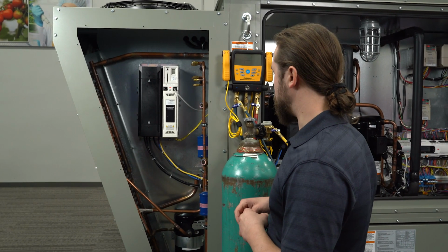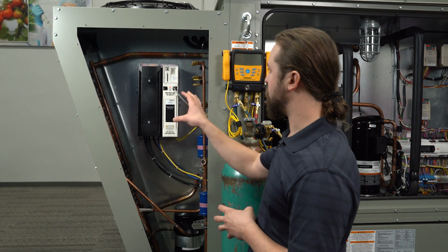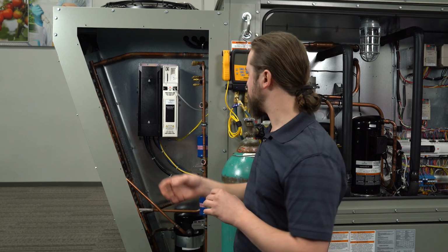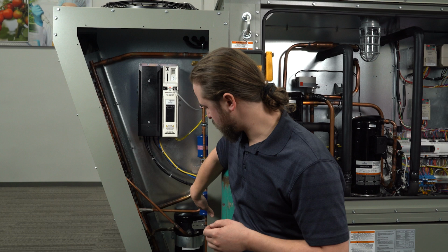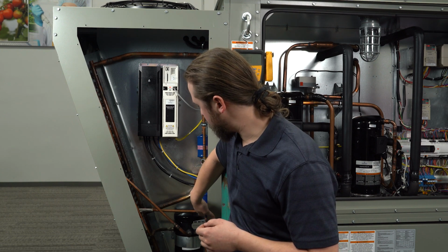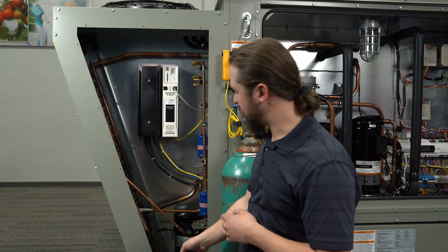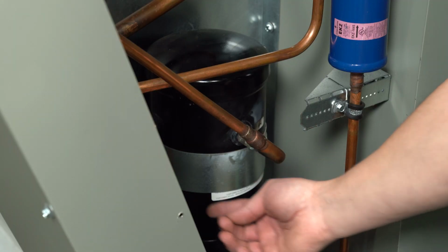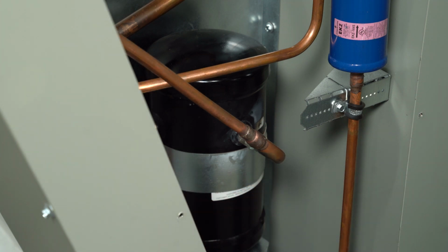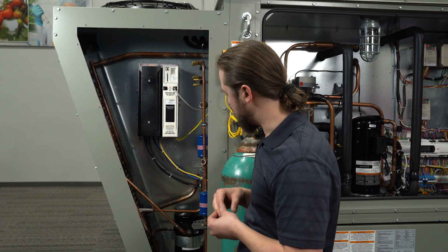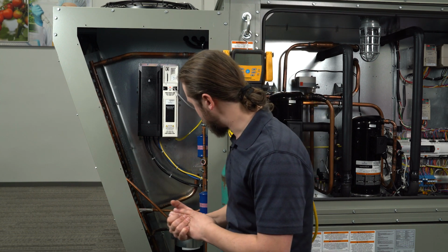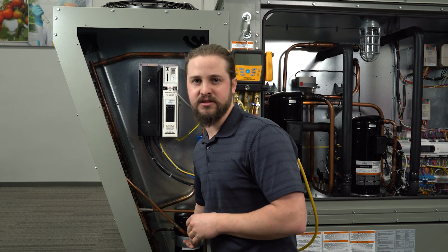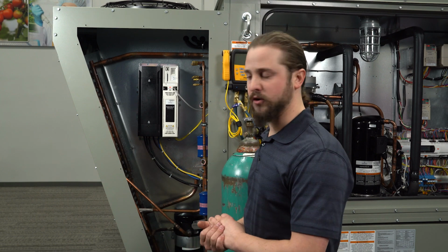Okay, another compartment that we want to take a look at is the condenser access compartment. Here you'll find your liquid line service ports, sight glasses, filter dryers, and for the context of this training, the liquid receiver. So the liquid receiver has steel to copper brazes. We use a flux and a 38% solder for that. You want to give that an extra set of eyes in your leak search as well.